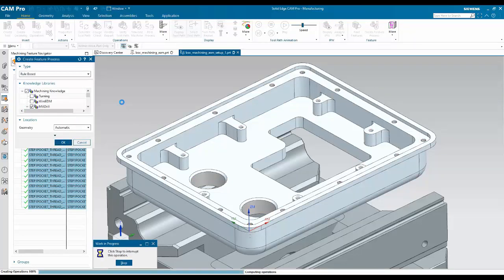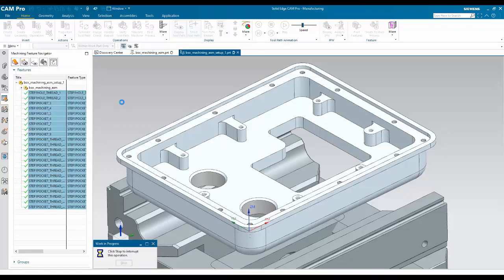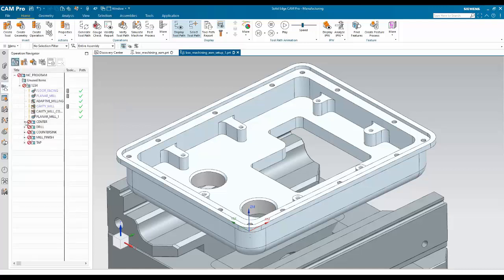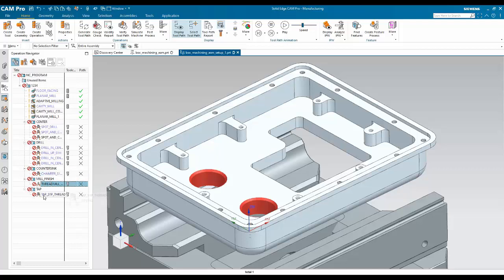It's going to look at the rules-based engine that we've created. This is out of the box, no messing about. I've not changed this in any way or form, and it's automatically applied toolpaths to centre drill all of the part, drill all the part, countersink those, thread mill those holes, and tap those. Really quite simple.